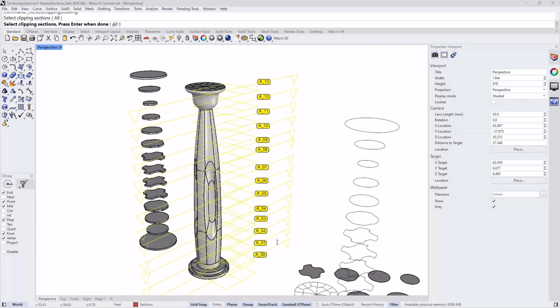And these two curves need to go to two separate layers so that the laser cutter knows which one is the upper and which one is the lower. No, they need to be smashed onto one layer, and then you find the maximum perimeter of those two curves. Oh, and you union them basically. Yes.